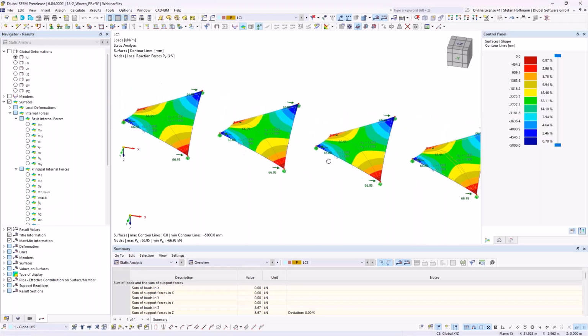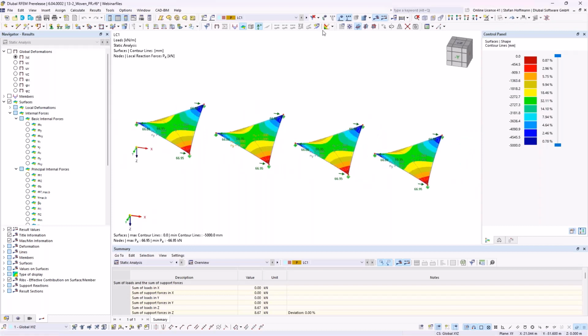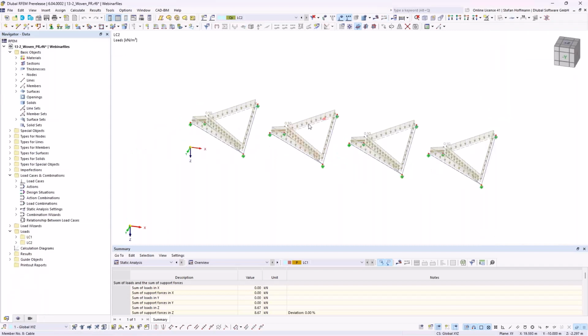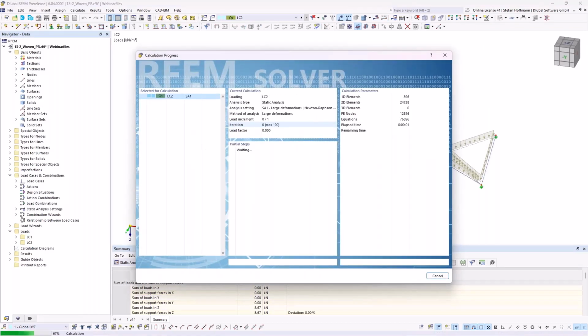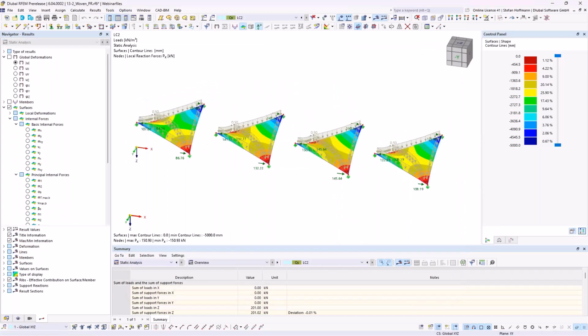But still, as told, we receive the same results for our form finding process because the boundary conditions are the same. And due to the fact that we define the pre-stress, we will receive in this state the same shape. If we now apply a load to our form found structure, all the material properties and also the boundary conditions, etc. come into play. So even if you now would have members, the stiffness of the system will now be given a bit more attention than it is in the form finding process. Also, the pre-stress will maybe redistribute if you use some form finding supports. I will show you soon how they are used.